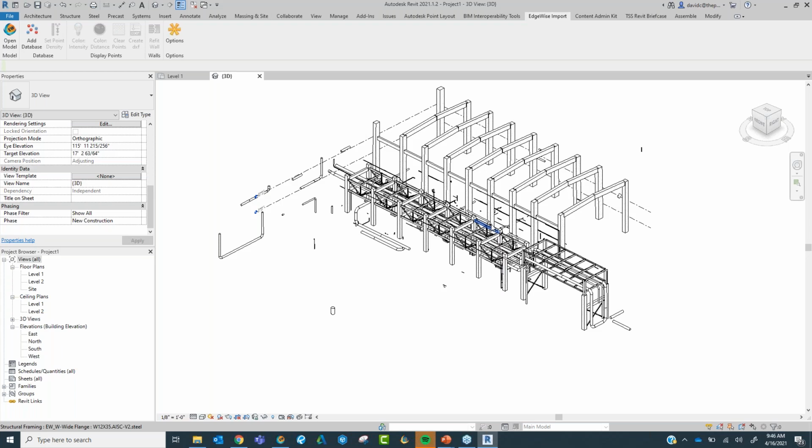At that point, you want to kind of look at, okay, I know my scanner is going to be able to get from here to here, kind of line of sight, right? And that's where we can go ahead and start planning. Like I know that I need 2 or 3 setups to get all of this information for this specific element or this room, what have you.